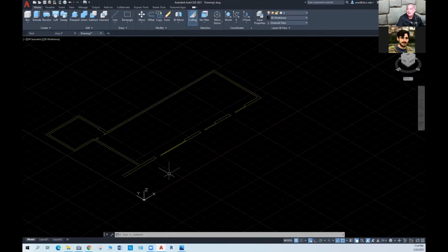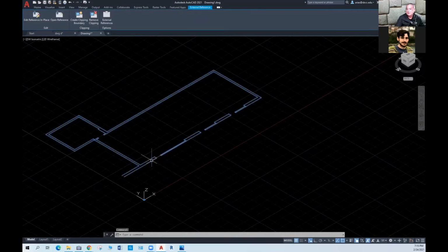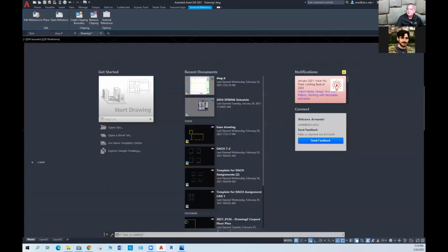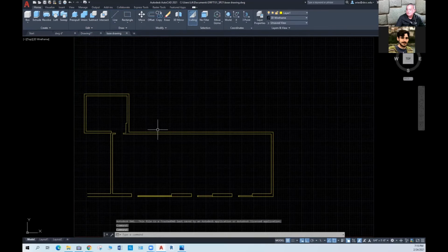And so now that I have this object here, I can start creating geometry in 3D just by using that profile. And there are some tools that are going to allow me to do that. But obviously, inserting as an XREF has its pros and cons. And in AutoCAD, actually, in my case, I prefer to copy and paste the view in 3D.